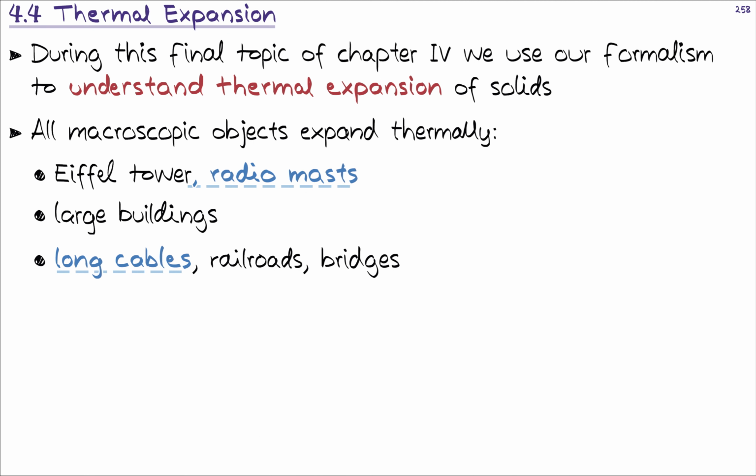Another example would be the wheels of a train and how they are secured underneath the train. Because trains are so heavy, we cannot really use normal bolts and nuts to secure the wheel of a train. Instead, the wheels are put into place onto a more solid piece of a rod by heating up or cooling down the wheel and the barrel accordingly.